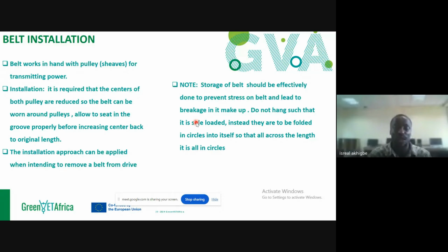In that case, that is similar to what? A foundation and balancing. I am giving us a layman example to be able to connect what I'm saying. So if you put that generator on a rubber tire, what happens? Once it's vibrating and in operation, the rubber tire helps with taking the shock of the vibration, and also prevents it from moving because of vibration from where it's not intended to be.